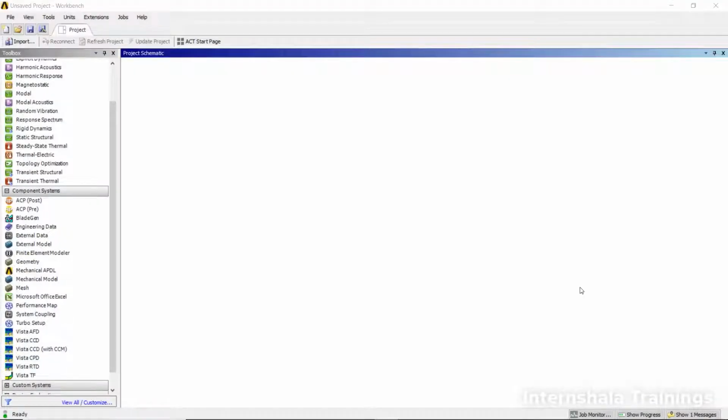In this lecture, I am going to introduce you to Ansys Design Modeler. Inside Ansys Workbench, we have two types of geometric systems. One is the Design Modeler geometric system, and the second one is the SpaceClaim geometric system. If you want to create simple components and edit data that has been imported from other CAD systems, you can efficiently use the Design Modeler. If you want to create advanced parts and advanced assemblies, then you may use SpaceClaim.